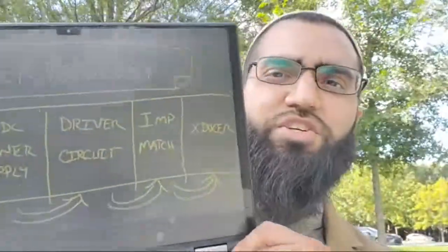So an impedance matching circuit is needed in that case, and that could be a combination of things, but the simple idea of it is going to be a transformer. If you need more voltage or smaller voltage, you transform that voltage and current into what can best drive power into your transducer. If it's a higher impedance transducer, you're going to need higher voltage. If it's a lower impedance transducer, usually drive circuits are naturally suited for high current, low voltage. That's many of the chips you'll find.